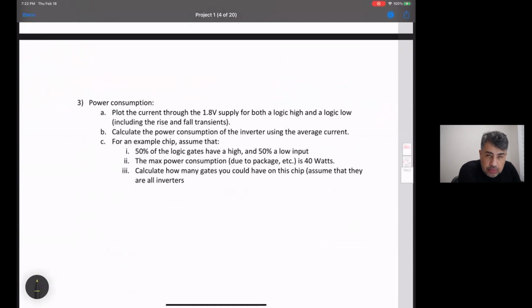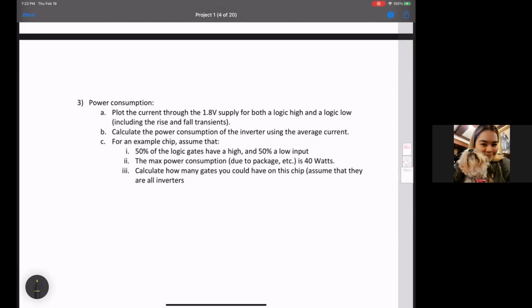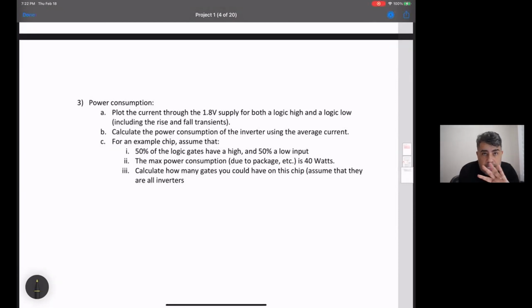So I'm being really annoying with this project, because I'm forcing you guys to deal with this NMOS inverter to show you how much better the CMOS inverter is. I think it'll help you understand the CMOS inverter much better. We see the noise margins aren't so great. Delay is funky. You guys should be seeing very different delays between rising and falling. All that stuff's bad. And then the last thing is the power consumption is going to be relatively high.